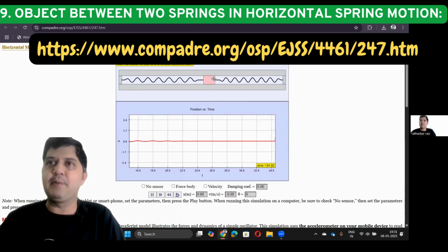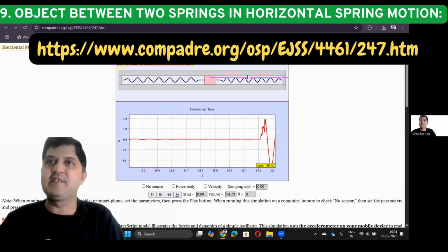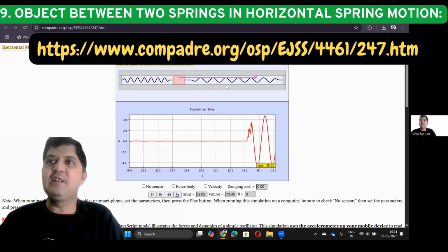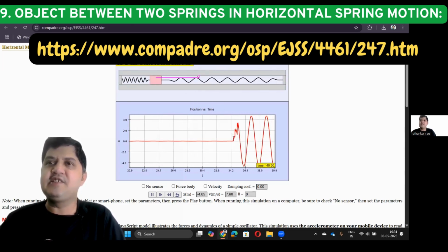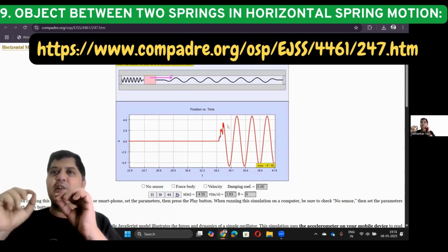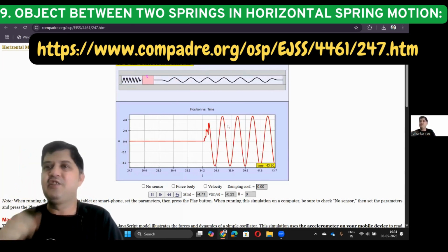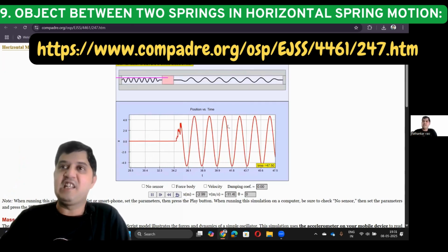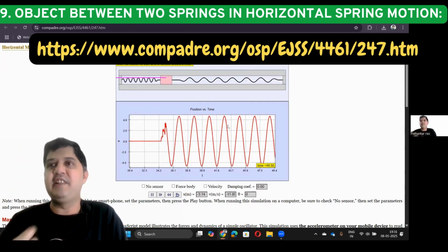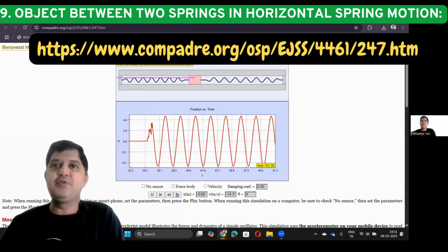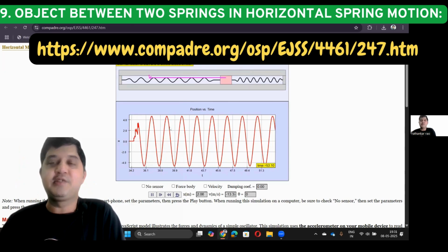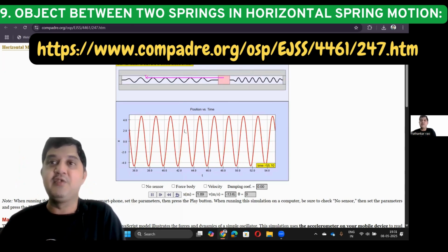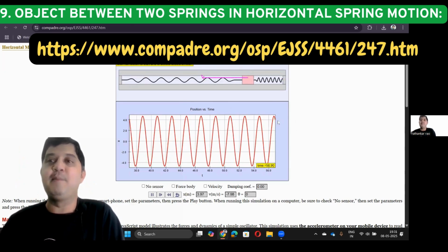Now what will happen is a question. So I oscillated like this and left it. You see the velocity vector is like this. Now why is this seen here? Because my hand shook a little bit, and as a result you got those small changes over there. These things you should know. While you conduct an experiment tomorrow and record the readings, if you get something like this, you should leave 1 or 2 cycles, and from there only you should start. Now you see you're getting constant amplitude over here.